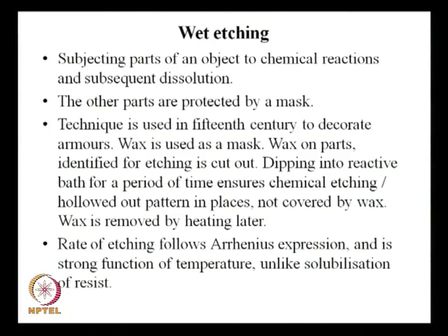Welcome to this class of microscale transport process. What we are discussing is various microfabrication techniques, in particular photolithography, and we have already discussed how to transfer a pattern using a mask and a mask aligner, what is the use of photoresist, and how this photoresist is coated on a silicon substrate. These points we have already discussed. We start this class with a discussion on wet etching.